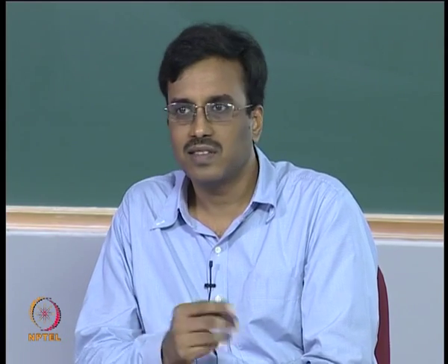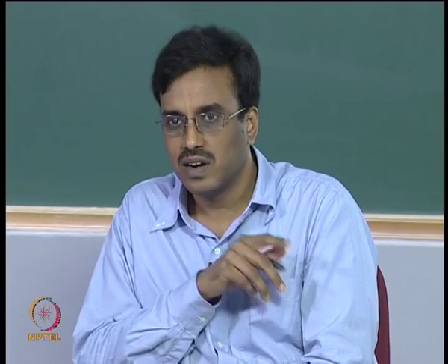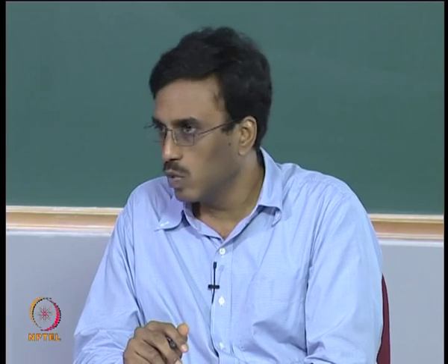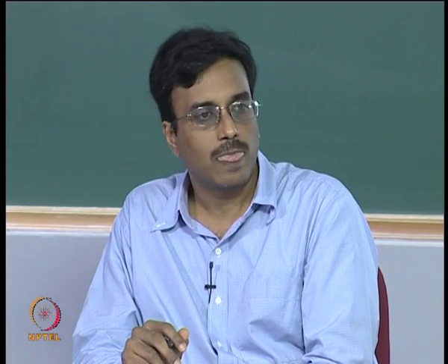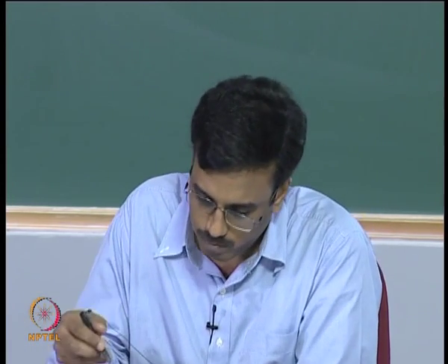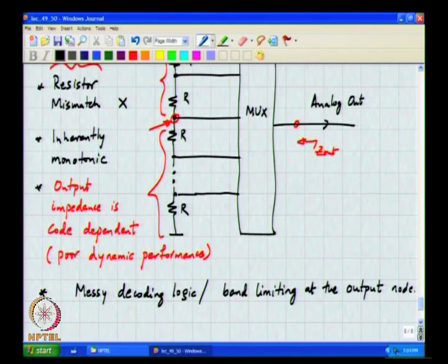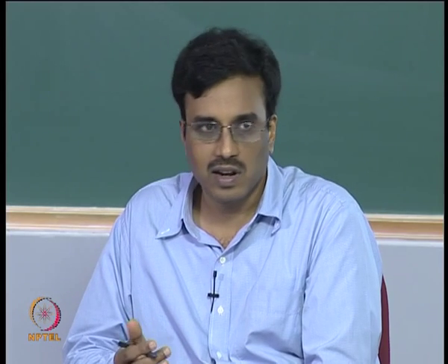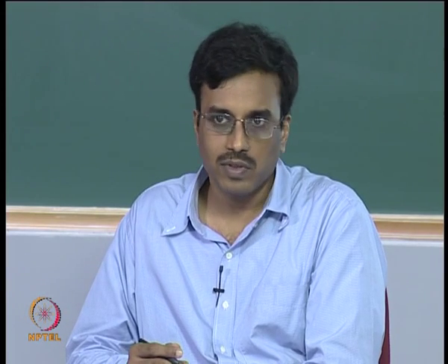The nice thing about this is that it is inherently monotonic, and the fact that the decoding logic is messy is also a problem. So, you use it in places where the logic does not get too messy, in other words where the resolutions are not very high and when you are not really interested in dynamic performance.